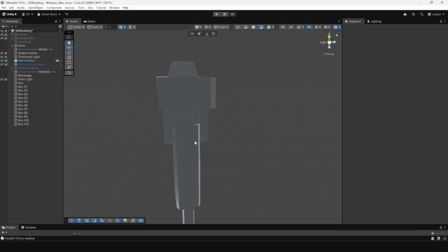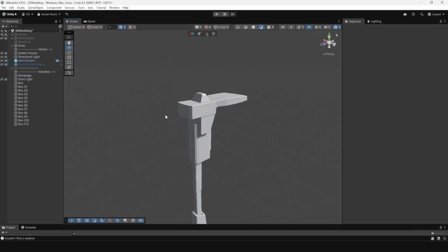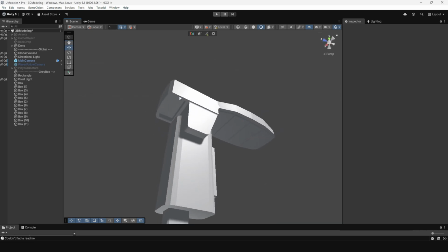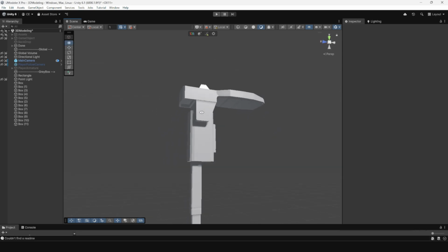All right, so there's a couple ways we can probably do a cable. We can use the follow tool, which is pretty easy. So the follow tool just requires a couple different things. One thing that we need is a line, and the second thing we need is a face or a polygon for that to follow.